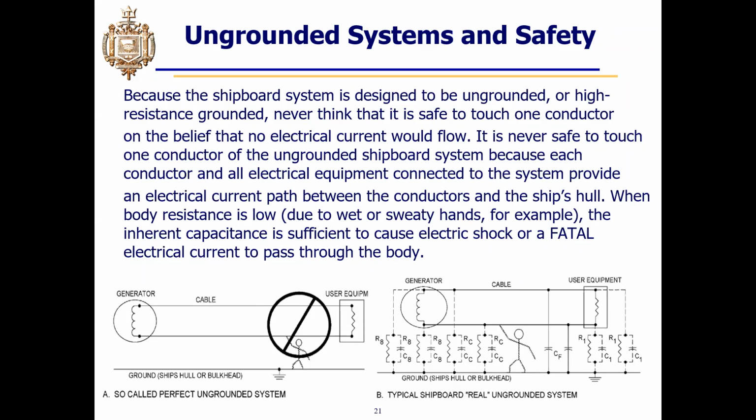In this case, we can see on this bottom right picture that the resistance is not infinite. It's some high value. It could be 5 megohms, for instance. But there's still some path for current to flow to ground.